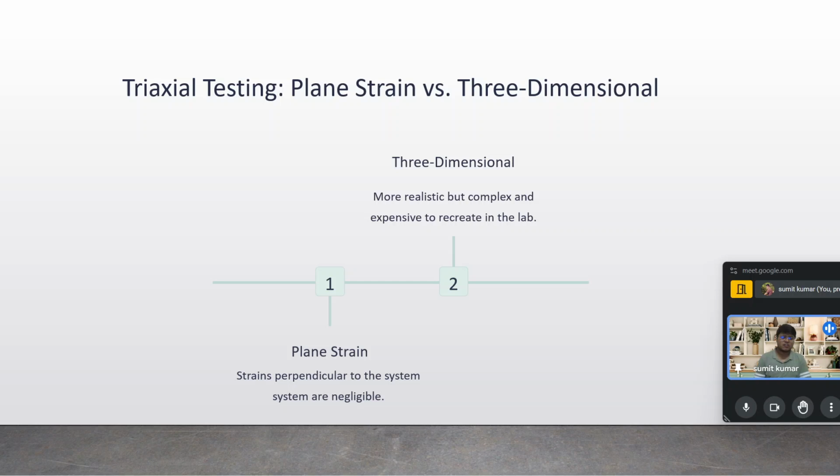When the value of deviating stress is known, sigma 1 and sigma 3 are known, and we know that specific condition. We talk about the three conditions, the UU test, CU test, and CD test, and we understood that in the different conditions we consider C and phi as 0 depending on the requirement when we are solving, and the other information is not known to us. So how are we able to know those parameters which could be used in finding the shear strength of the soil? I think that is clear. A term came up here, so that's why I took some time to revise those terms.